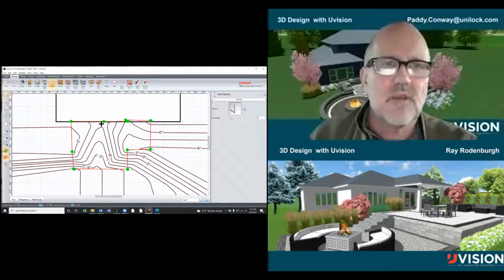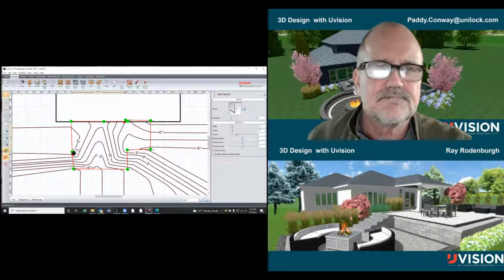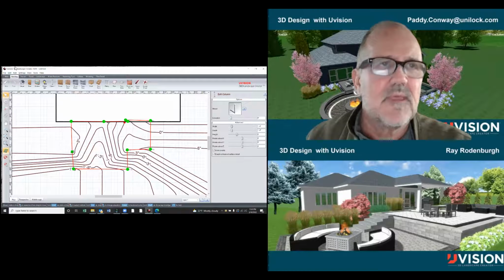I go to the word column, and I'll drop a column at the front door like I did with the other pictures. I'm going to be blatant, and I'm just going to change the color so you can see it. Edit materials, solid color, red, okay. Edit, copy, edit, paste in place. And I'm just going to go around all these different things and leave a red flag marker, paste in place. Turn off the magnet. Edit, copy, edit, paste in place.